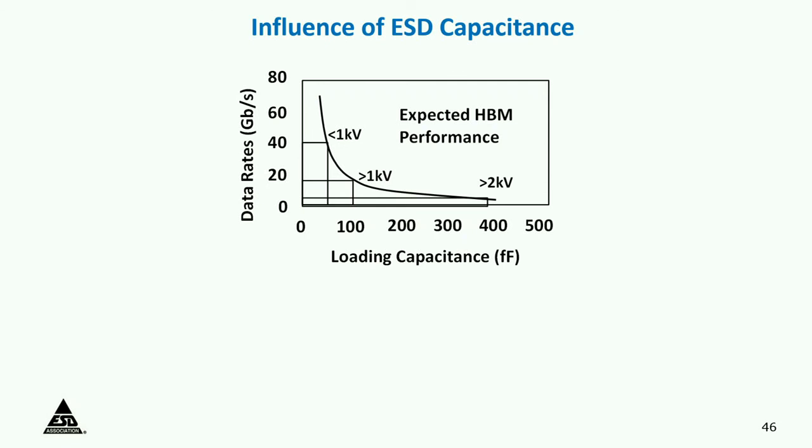I'm just interested in the design flow of the ESD. If I have circuits that are very sensitive to the impedance, like RF circuits, then they have to have some impedance matching that needs to be done. So once it's designed and you add ESD protection, what if it's going to affect the matching? It's a real challenge.